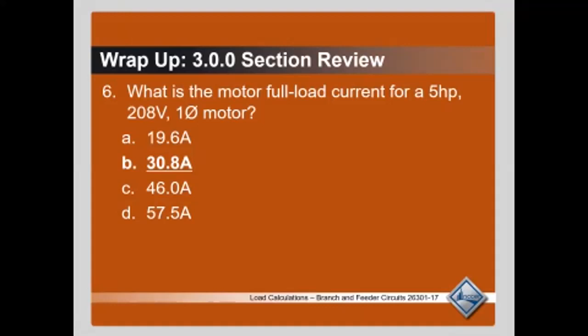Single phase, 5 horsepower at 208 volts equals 30.8 amps. It's literally in that table. If you look on page 70-321, right there. So there you go. Find 5 horsepower and look at 208 volts. 30.8. Yep, 30.8.